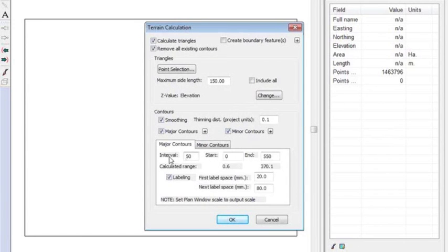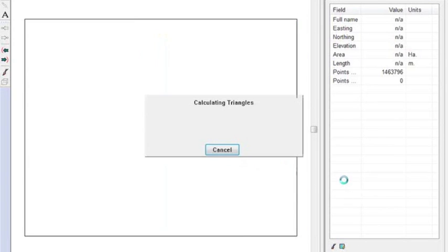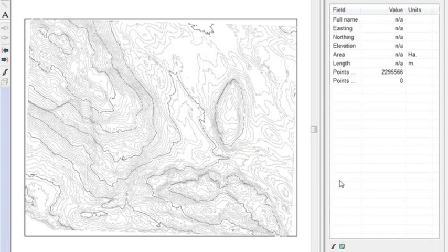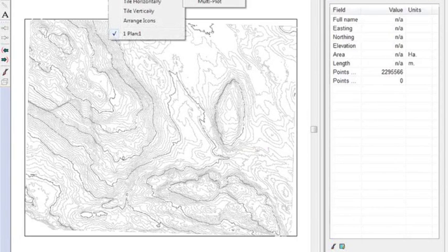So let's just do a TIN surface here. And I'm going to put on contours 50 and 5. That sounds reasonable. Let's not bother with labels. Now, this is just one little tile. And generally, LiDAR comes in tiles. They're rectangular and have been created for you for convenience. And this tile contains 1.5 million points. If I had 50 tiles, I would have trouble doing this. So there it is. Looks good.